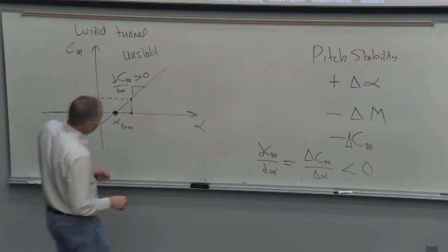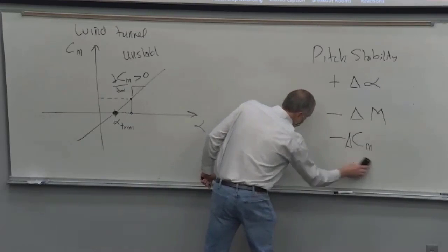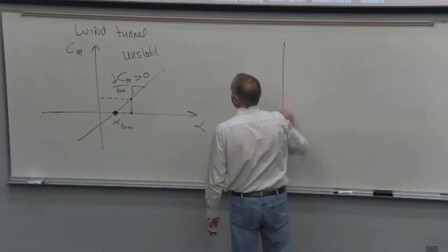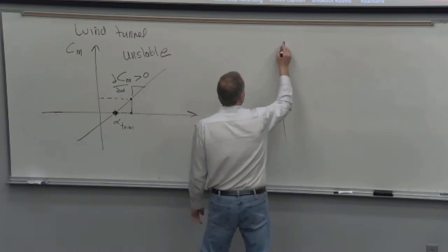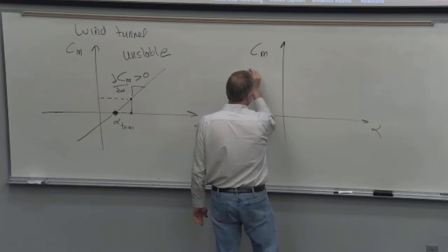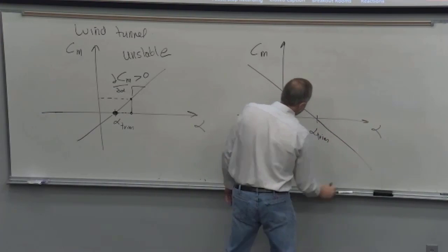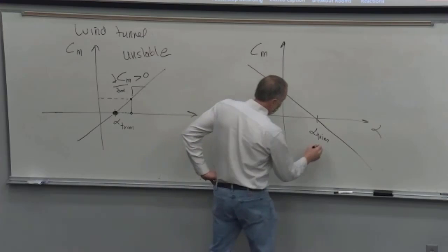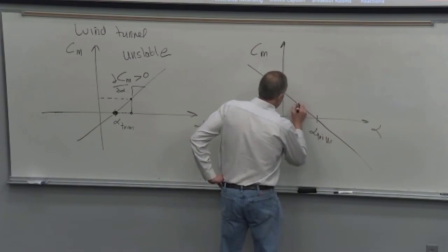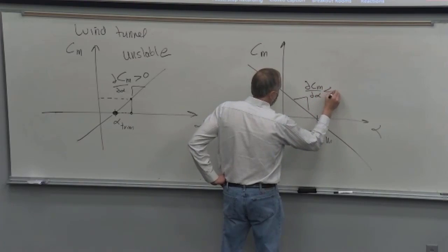So what you want is the opposite of this. We're still okay on time, or yeah, okay. So that's unstable with an E at the end. What you want is to go into the wind tunnel and you see a plot like this. Again, this is trim because the pitching moment there is 0 at that angle of attack. And this has a slope that's negative.